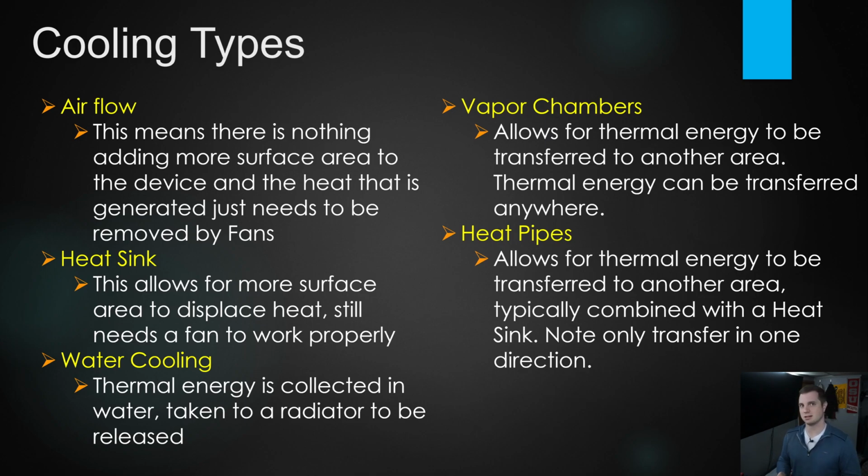The difference is that you don't need as much space for a vapor chamber as you do with heat pipes. So a vapor chamber is exactly the same performance, it just takes up less space to get to the same place as a heat pipe. This is probably the reason why you're only going to see it on, one, premium products, and two, thin and lights, because it doesn't make any sense to not use a heat pipe if you have the space for it.